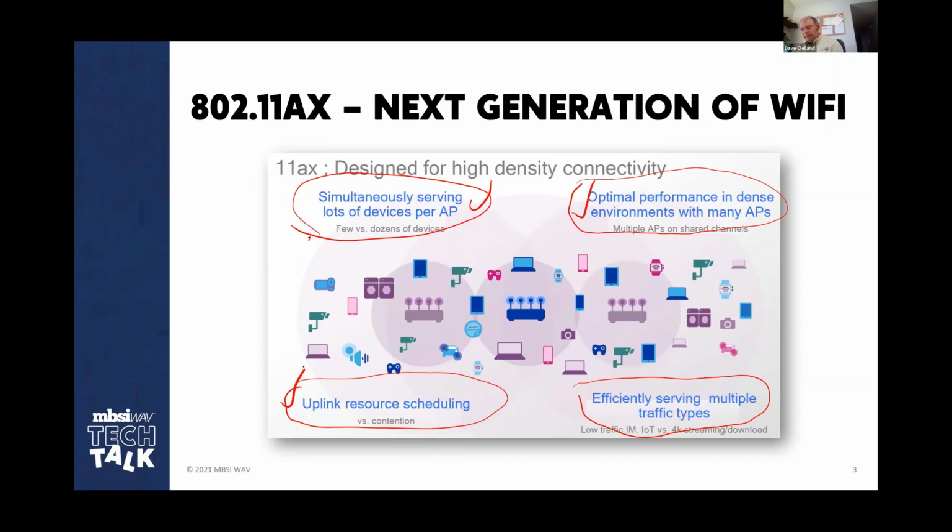And because of this scheduling, we can now serve different types of Ethernet traffic over the link, whether it's SCADA sensor traffic, which is typically very small frames, and sometimes very many of them, or regular surfing traffic, which typically requires low bandwidth in the uplink, and then when the website answers or the movie streams, it occupies a considerable amount of bandwidth. We can mix these types together now because of this scheduling, and accomplish that goal.